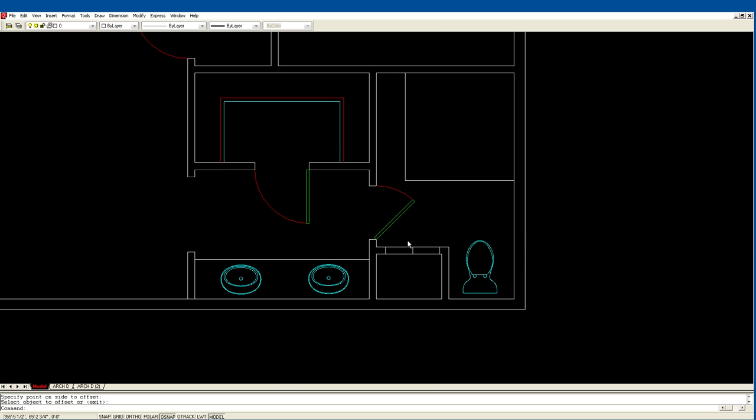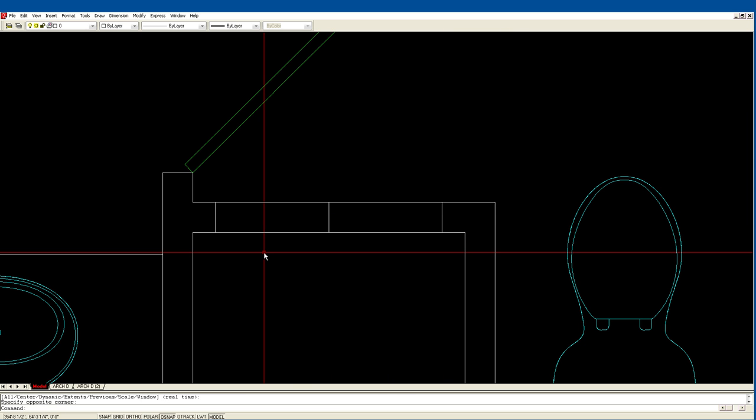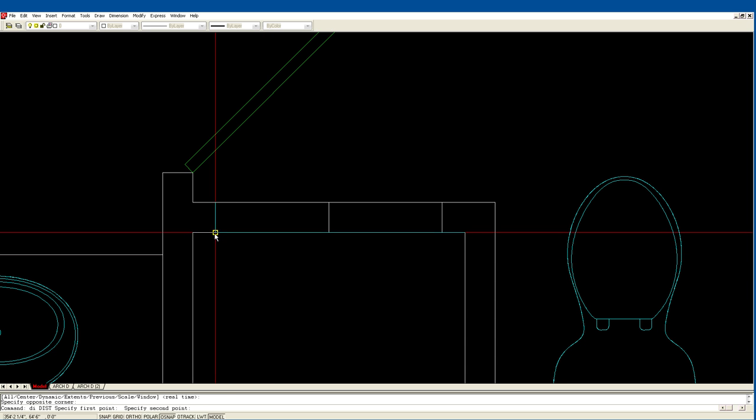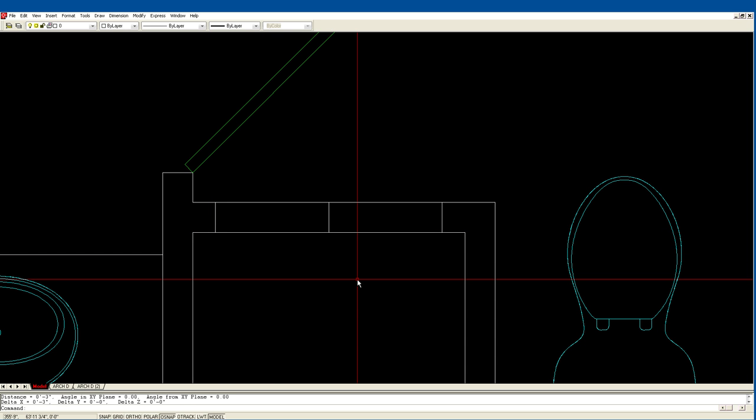Now why didn't that work? Oh, I know why. Let's move these 3, from this point to the center of that wall. Let's see how much room I got here. Distance from there to there, 3 inches. Well, bifold doesn't need as much room. You still have to have the 2 studs, which is what you're going to get, and then you are going to have an inch of drywall. So that's almost perfect.